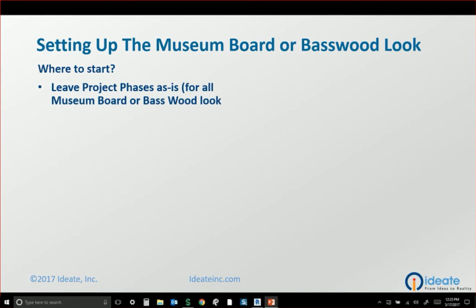That's kind of like people freaking out with the whole bilayer versus not bilayer, right? Okay, well, this is going to be one of those situations. The first thing I always recommend, if you're going to be tweaking any of the settings, is to take your current design documentation model and do a save as and make it a presentation model, all right? Because you may upset some folks, if you know what I mean, when they come back to the model and everything looks like museum board.